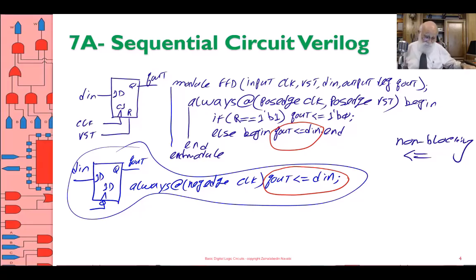All right, so this is something, and I'm going to do another flip-flop in a second, and then I'll add a few things to the output of it. Let me also say something about this positive edge here for the reset. Often it's asked, if reset is only level, that when it becomes 1, the flip-flop resets, so why do I have to have posedge? See, the reason is this.